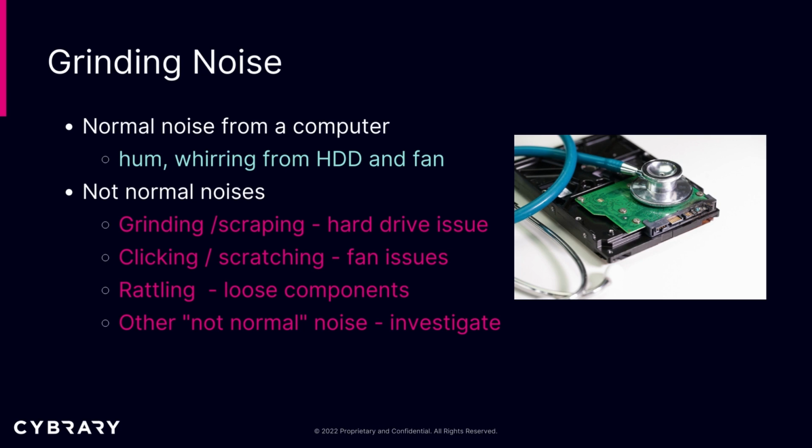Grinding noises. This is a noise that you should never hear from your PC. Now, there are moving parts, especially if you're using an older magnetic drive. Those drives normally make a hum or a whirring noise. From the fan, you'll get a hum, a whirring, or a constant noise like that. But you wouldn't get an abnormal noise like grinding, scraping, clicking, scratching, rattling, or anything like that. If something is grinding and scraping, you want to look at your hard drive.